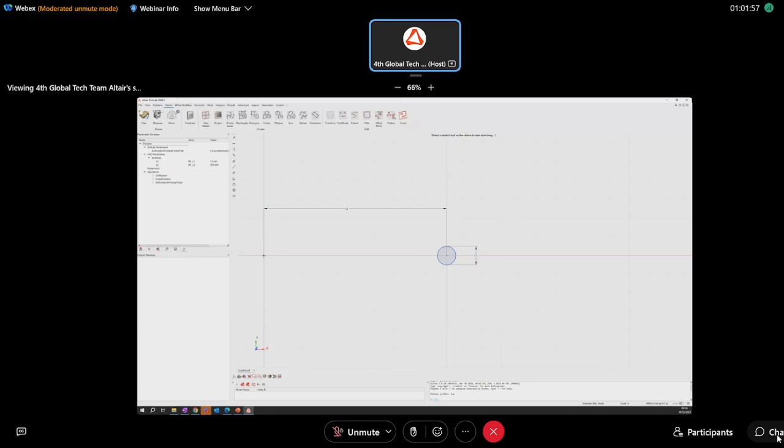Now we need to create the air around to visualize the magnetic field on it. So the model can also be solved without the air around that we are going to create, but at the end you will see just the quantities on the wire, right? So for this reason, we are going to create the air around.